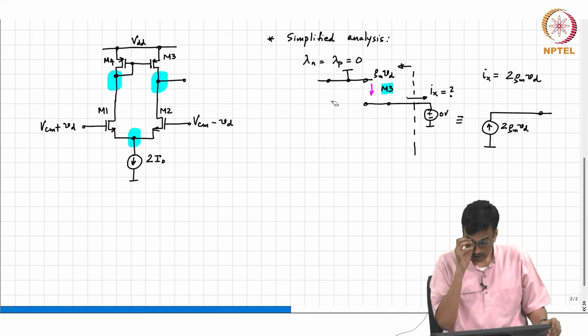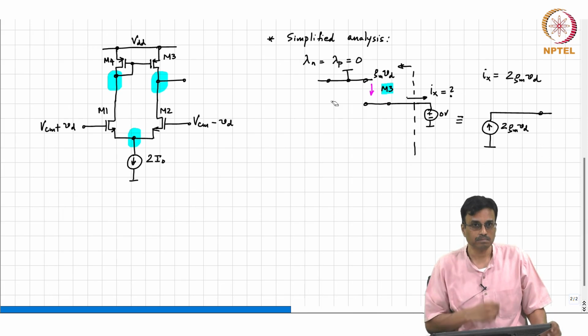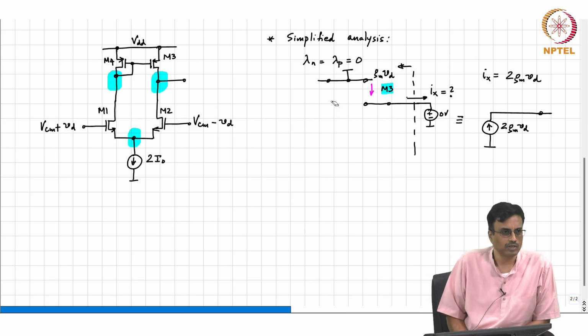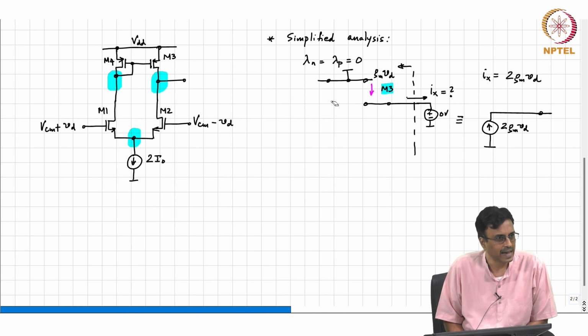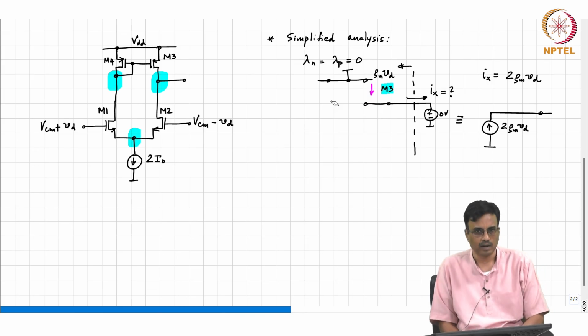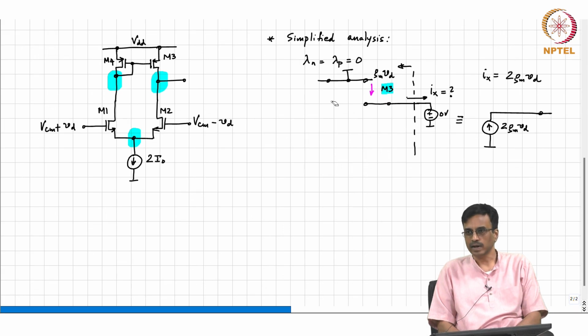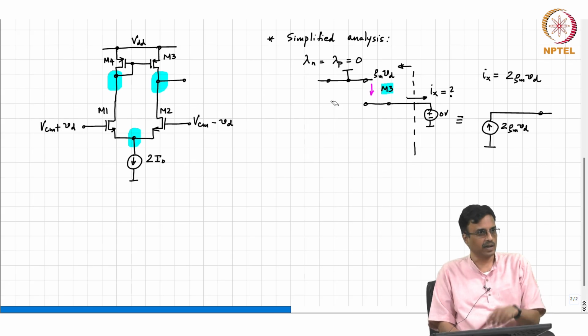Yeah. So, just like how we had in the common source amplifier with an active load, if the output impedance of the transistors was infinite, then we got an incremental gain which was infinite, correct. Same thing happens here. Okay. All right. So, the bottom line is that the M4 transistor is useful after all, right, because it gives you twice the short circuit current.